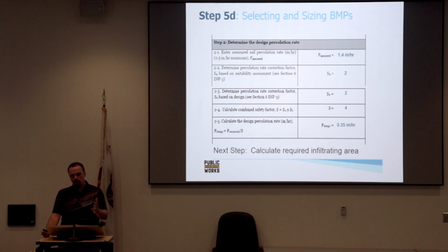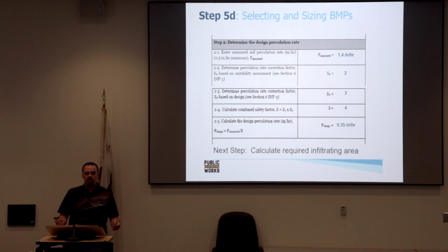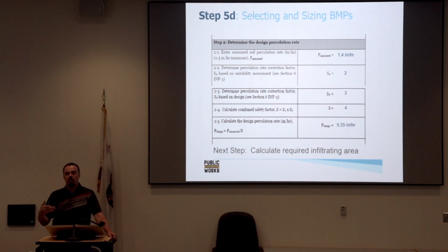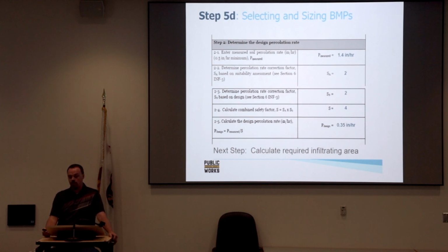There's even one part in the infiltration trench design fact sheet. It says if something is draining faster than 2.4 inches per hour, you have to have full pre-treatment before it. Nowhere else in the TGM is it mentioned. It's just copied over from one of the other things, and no one caught it when we were reviewing the document for approval. So a lot of it is regurgitated from other manuals.